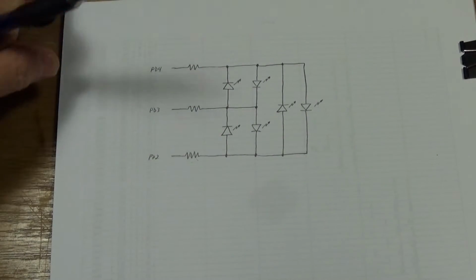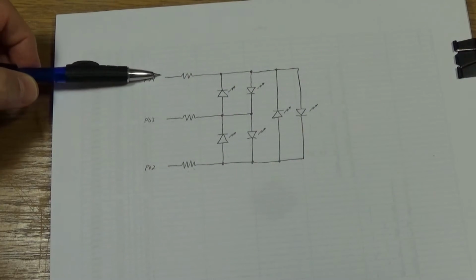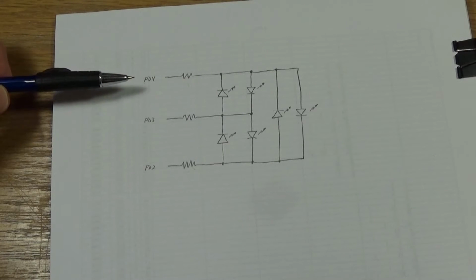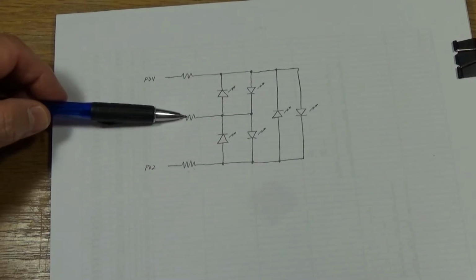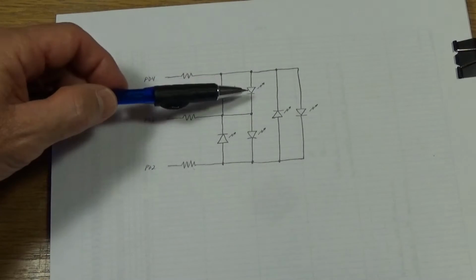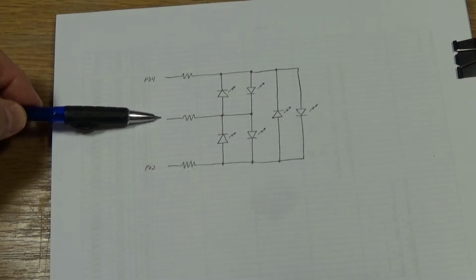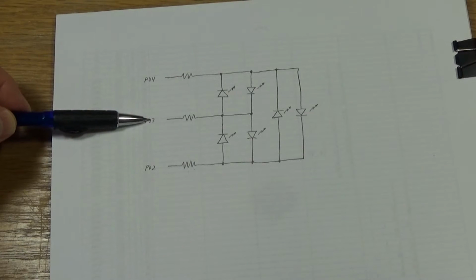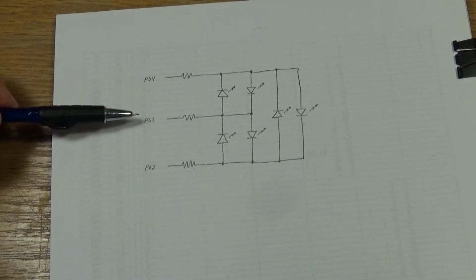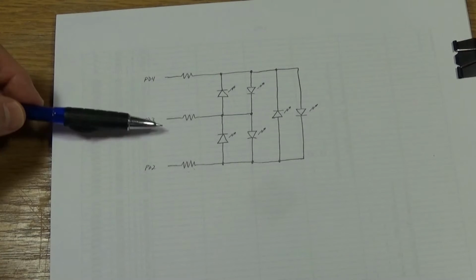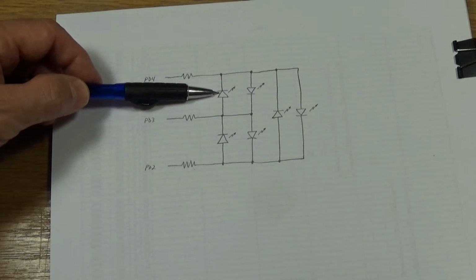And what you do is under software you just control the data direction for each of these pins, whether it's an input or an output, and also whether it's high or low. So if we just look at these two I/O pins here, if we wanted to illuminate this LED here, we could turn both of these I/Os into outputs, make this one low and this one high, so it would drive 5 volts through the LED and through the circuit here, and it would light this LED. Keeping these both as outputs, just change the states of both of them. So this one's high and that one's low, this LED lights.